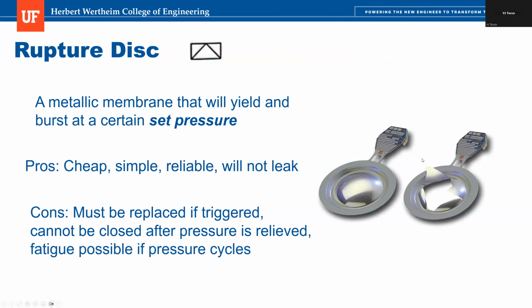In contrast, the pressure relief valve would open, allow the pressure to be relieved, and then it would close and reseat itself. The other possible downside of this is that fatigue is possible if there are repeated instances of elevated pressure that don't necessarily exceed the set pressure.